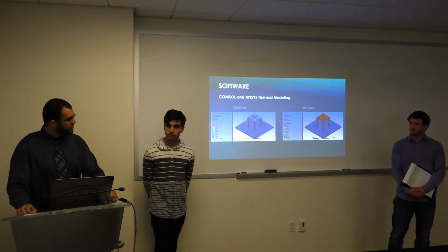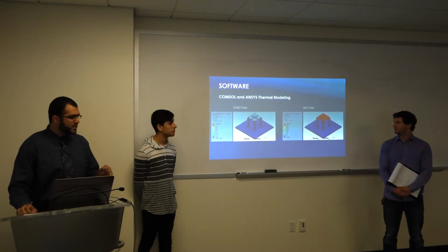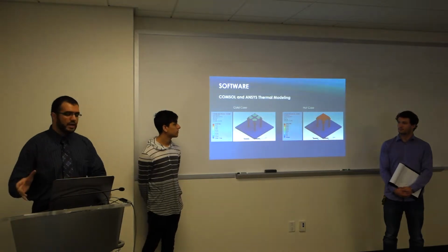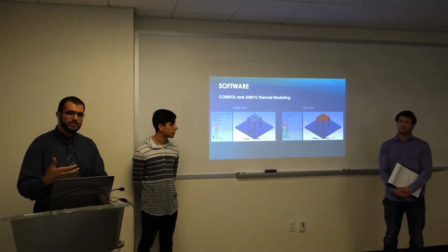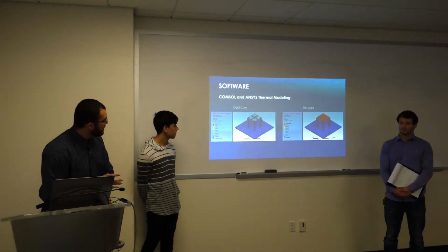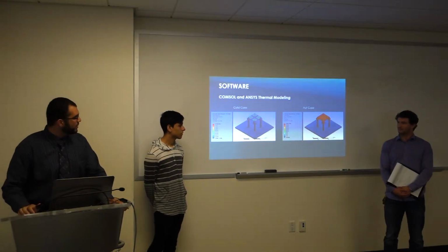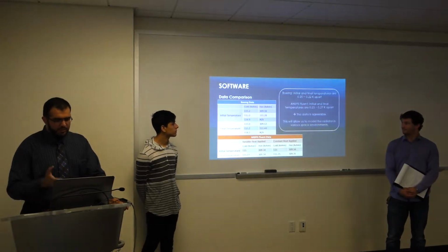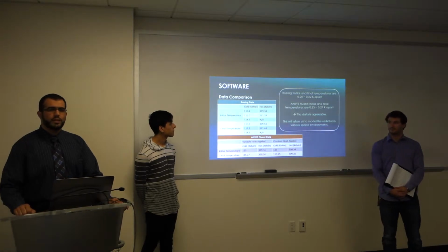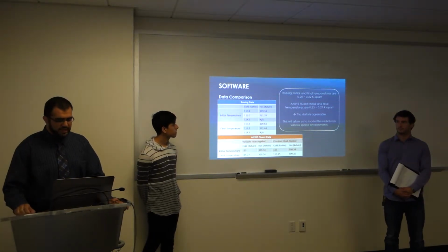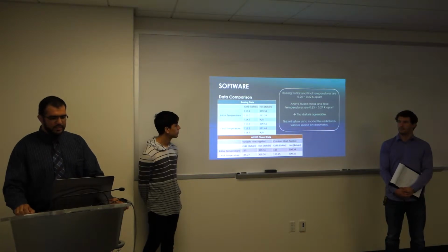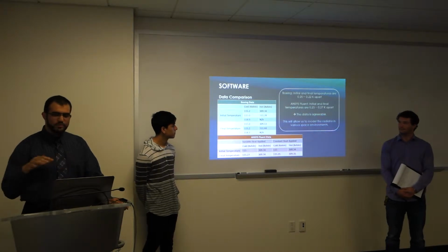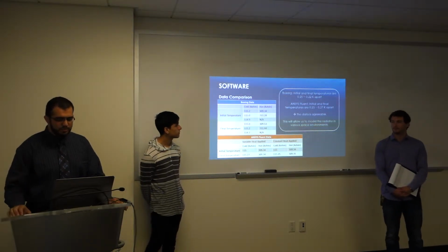So here we see demonstrated the cold case, when the CubeSat is not facing the sun, and the hot case, when the CubeSat is facing the sun. When you have heat applied to it, and when it's on the cold side, no heat applied. From that, we were able to grab some data from the software and correlate it with the data from the Boeing test. We graphed the data from Boeing, and we saw three points for upper cold and two major points for hot.